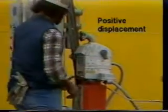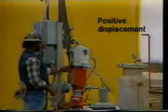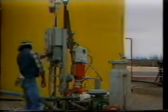Positive displacement meters are highly efficient fluid motors used for measuring oil volumes. The fluid stream is divided into segments within the meter, and the movement of these segments through the meter is registered on a counter. Now that we understand the options for handling crude oil at the surface, let's turn our attention to the gas stream as it leaves the separator or as it is produced from a natural gas well. In the case of produced gas, we are concerned with the removal of condensate, water, and corrosive or poisonous gases.